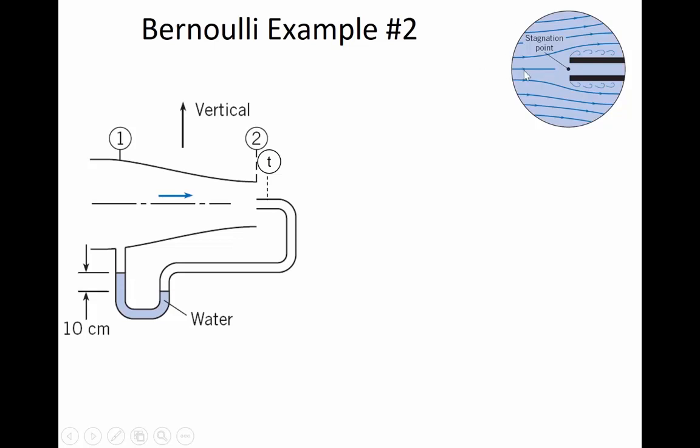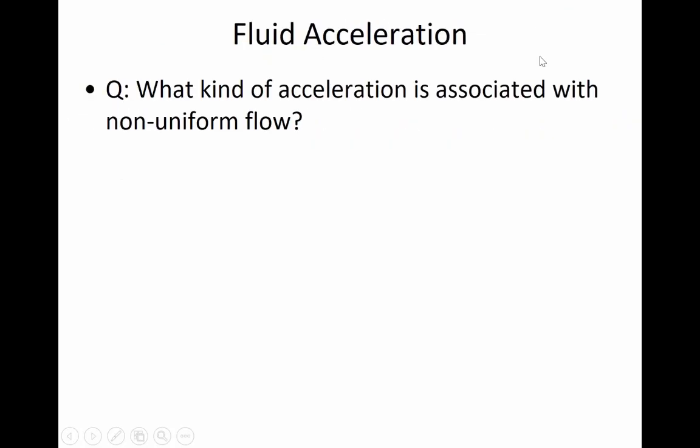And so there's energy in the form of velocity, and suddenly that velocity comes to a halt right at the opening of that stagnation tube. What that caused was a localized increase in pressure, because all of the velocity head energy was instantly transformed into additional pressure. All right, so that's the thing I want you to keep in the back of your mind: when you're intercepting flow, it causes a localized increase in pressure.